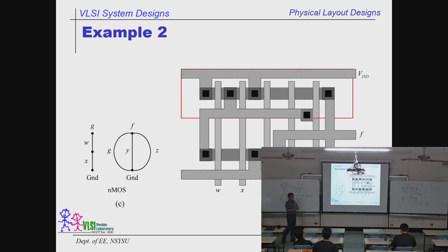See that? This is an amazing answer. Again, follow the Euler path. All you need is a single strip of diffusion for P and N individually, and it can be done. Because the Euler path told you that it can be done, then it can be done. In Chinese, it's 只要能够一笔画，就一定做得出来. Is that clear?